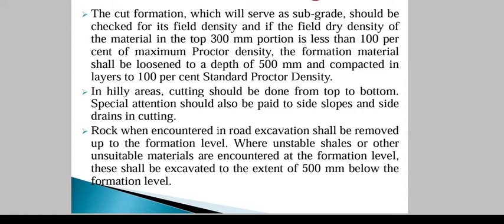If it is a village road, then the cutting height, as you have observed most of the time, is not very steep, or higher cut won't be there. That is a minimum of 3 to 5 meters of cutting most of the time. That's why in village roads, or less important, low volume roads, you'll observe n number of horizontal and vertical curves. To avoid the vertical curves, we go for cutting and filling, right.